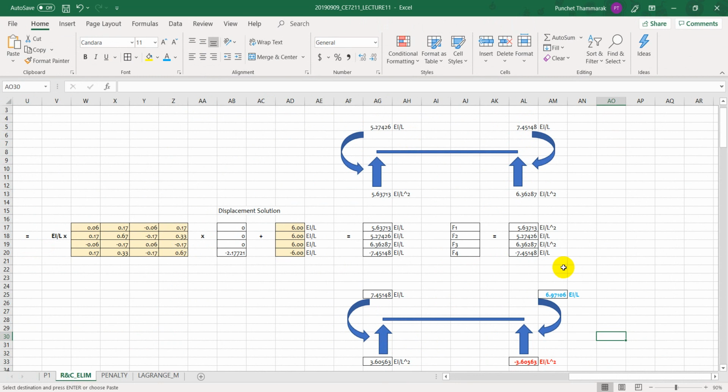Right. So if you draw this, basically you will need to do this because I think the sign has to be okay. I'll fix the sign a little bit, but first of all, you have to draw this. Once you draw this, you have this shear force, this bending moment, and then you can continue from this point in order to elaborate the diagram on individual member.